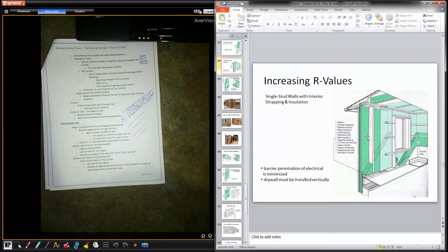Normally this wall would be framed first, and then you'd insulate, poly, and then frame the second wall, and then do all your interior partitions afterwards. So then the trades could come in at that point. You can see the rim wrap occurring here though, for this assembly, tying into that vapor barrier, which is in the middle of the two walls. 2/3 insulation outside, 1/3 inside.